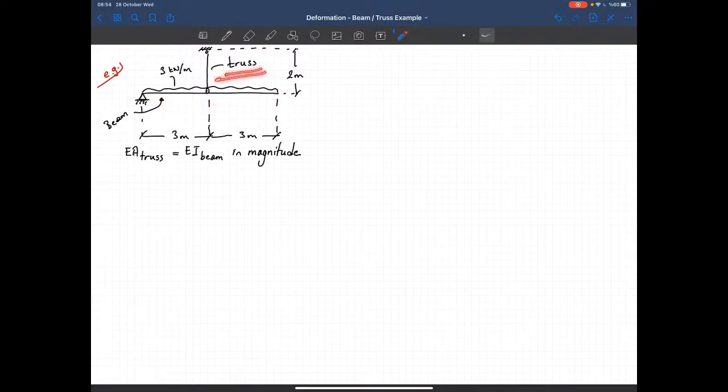Now I have a truss, so by definition it undergoes only the axial deformation. And take a look at it. I have a hinge here, so the moments are 0 at both ends, and I don't have any loading on this truss member, meaning that it doesn't have any shear or moment. It can only carry axial force. So in order to do that, first let's do the discretization.